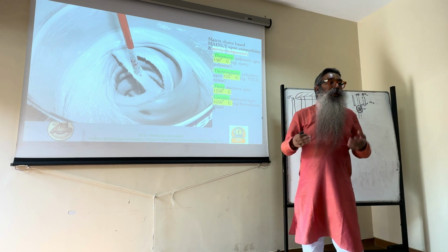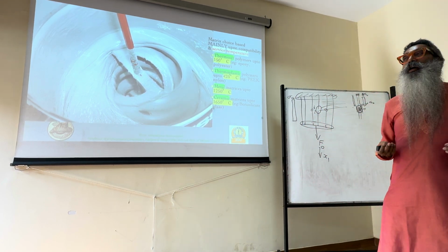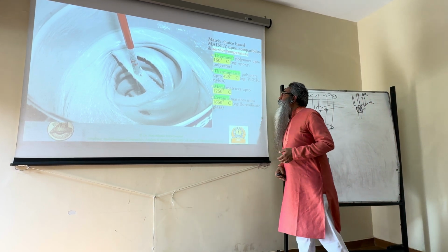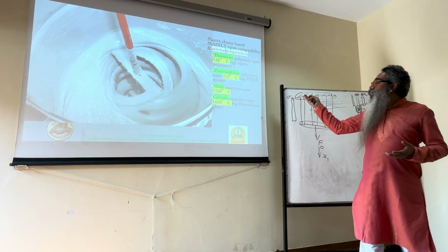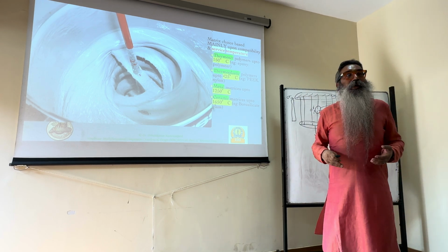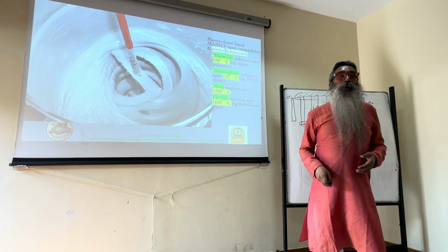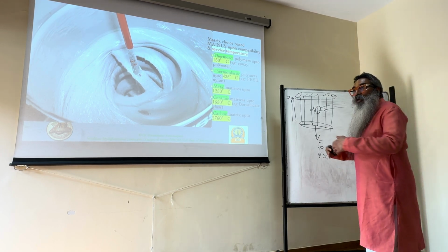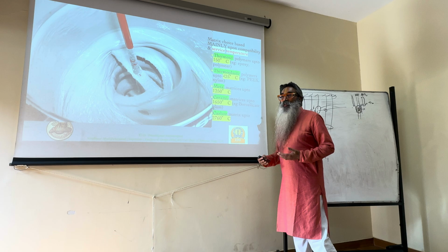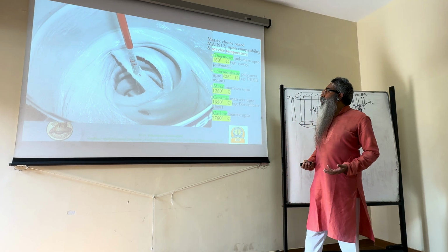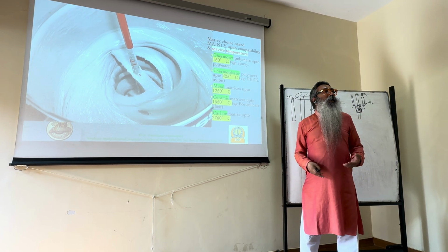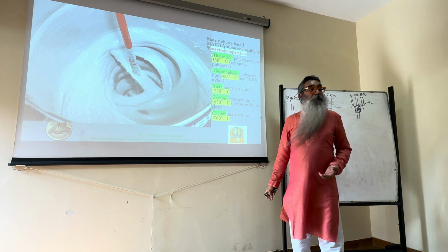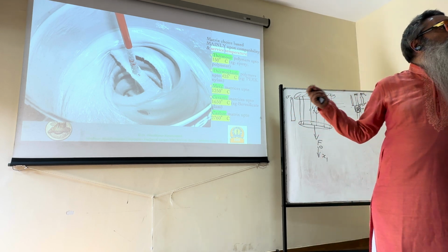Then if you have even higher temperatures, especially for a lot of space or re-entry kind of applications, then you have to go for ceramic matrices, examples being borosilicate glass, and that can take all the way up to 1650 degrees centigrade. Then especially for the frontal portions of the re-entry vehicle, where the aerodynamic heating is phenomenal, there you have to go for a carbon-carbon composite where the matrix is also carbon, and therefore it can go as high as 2760 degrees centigrade.